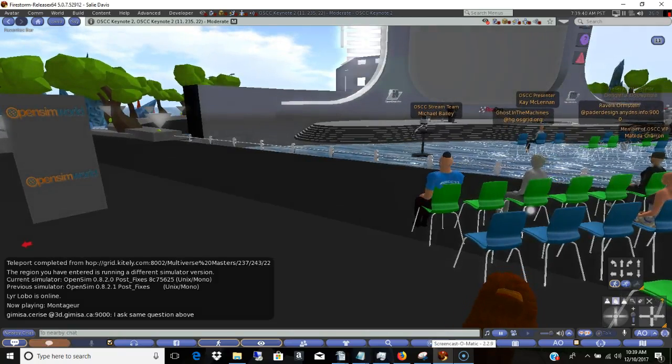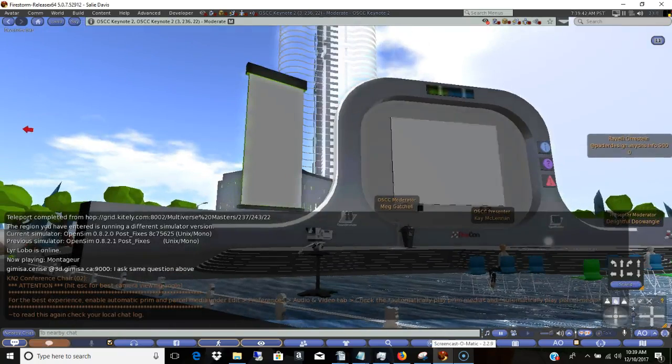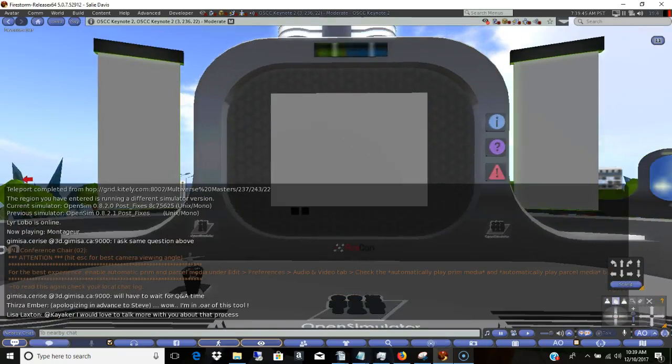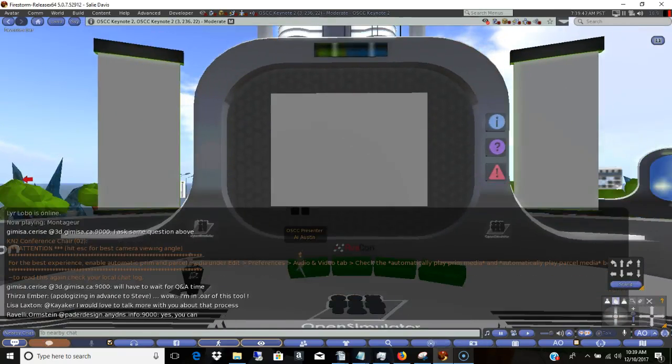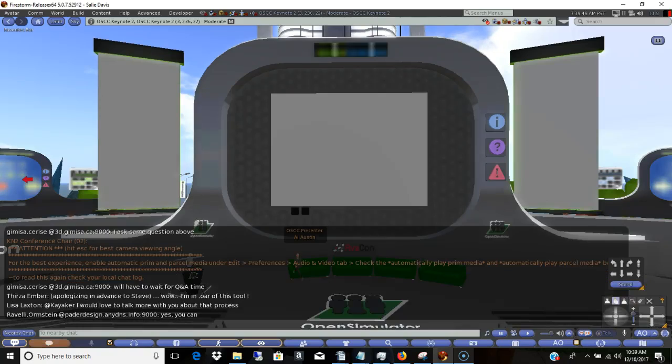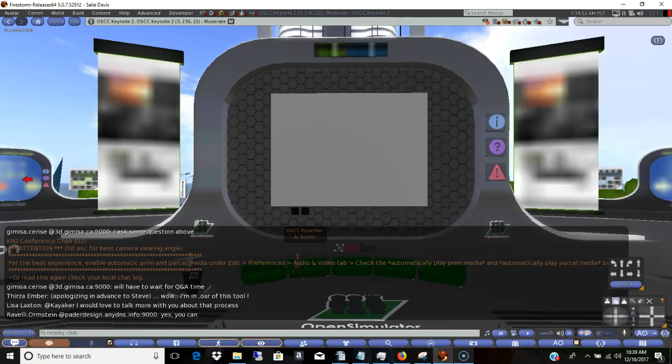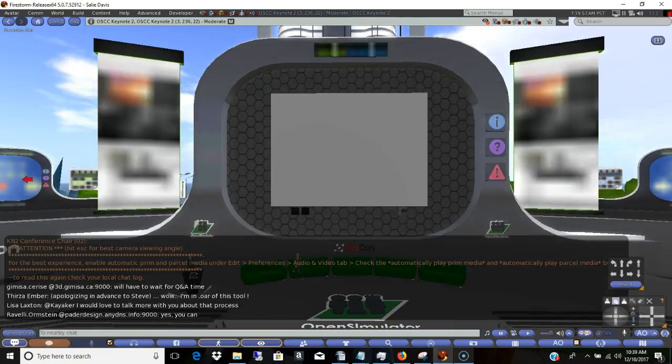The import to Unity is also pretty straightforward. The important thing is to make sure that you use a special shader that's made available in Unity before you take any content in. Anybody who's talked to me about this tool, if they've forgotten to do that, that's usually where they get a bit of a mess as things come in. The textures will all be wrong.